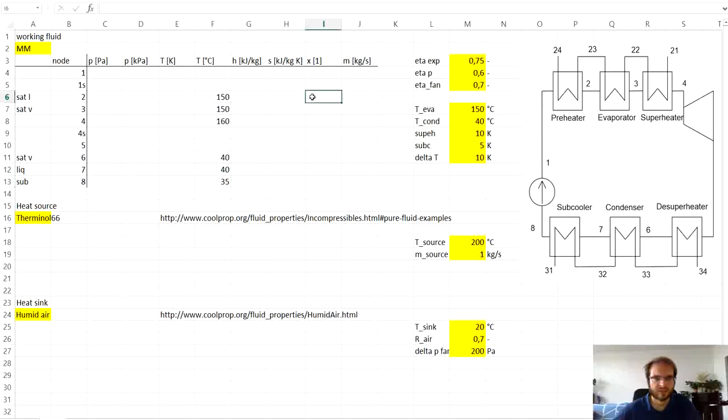So that means that at the point of saturated liquid, the quality of the steam is 0, and at the saturated vapor, the quality of the steam is 1. Similarly, those would be cases for saturated vapor at the point 6, beginning of condensation, quality is 1, and as the condensation finishes, the quality gets to 0 and the subcooling starts. So these are also, let's say, specified inputs, so we can highlight them.